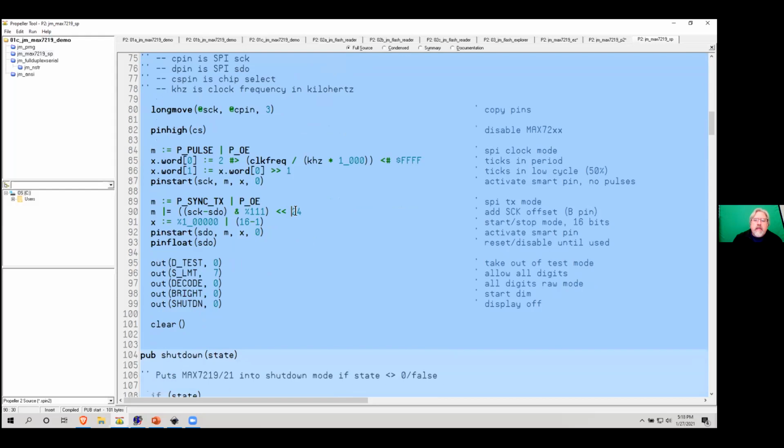Now, the way that this works is it needs to know where the clock pin is. So we're telling that if you look into the pins field, and I covered this last week, it gets a little detailed, but in the normal pin configuration, you can have A and B pins. You have to tell it where the clock pin is in relation to that data pin. This handles that and puts those bits into the right position. I'm presetting this for 16 bits.